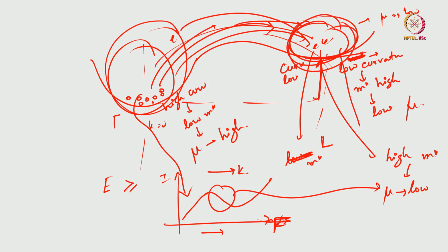The electrons in the other higher valley, this is a higher valley by the way, will start conducting nevertheless, because although the mobility has become low, the carrier density is increasing anyway, so you will get a high current here, okay, and that is the reason why you get a negative differential resistance in a Gunn diode.